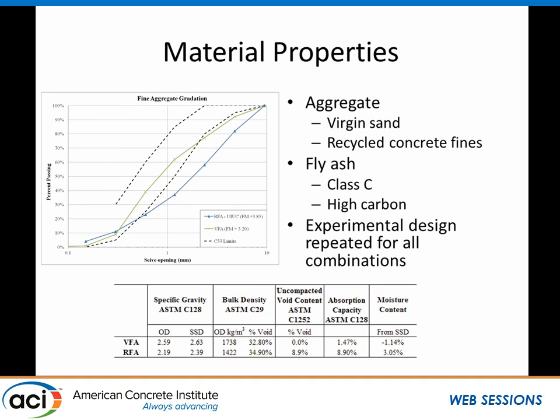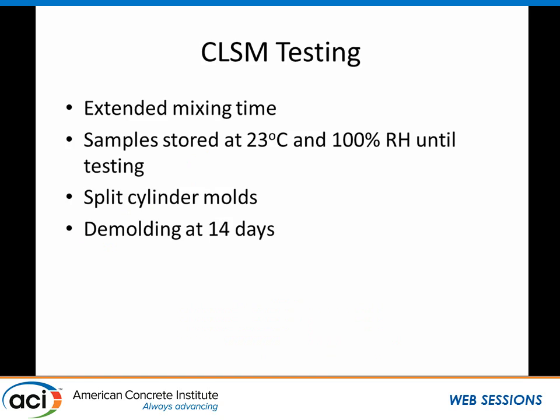We wanted to create a certain kind of comparability between our virgin sand and our recycled concrete fines. So we wanted to make sure we had the gradation of these things compared, and felt that they were generally comparable, and so we would not focus much on the differences in gradation as explanations for differences of fluid properties.